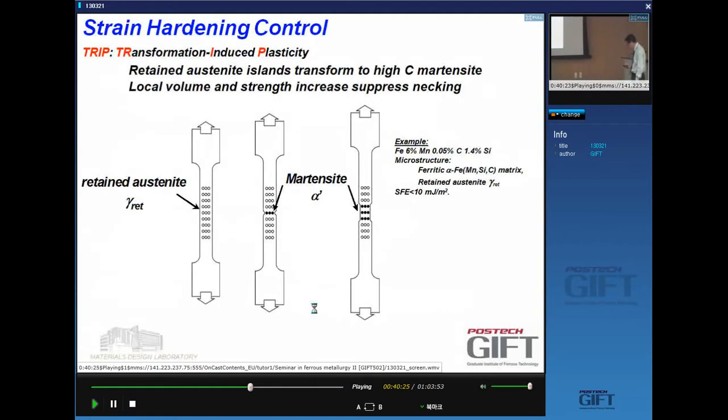Let's now look at the realm of the multi-phase solutions. Yes, and those ones are usually TRIP solutions, but I will end by showing that it is actually possible to have a multi-phase solution with TWIP as a plasticity enhancing mechanism. Plasticity or strain hardening enhancing mechanism.